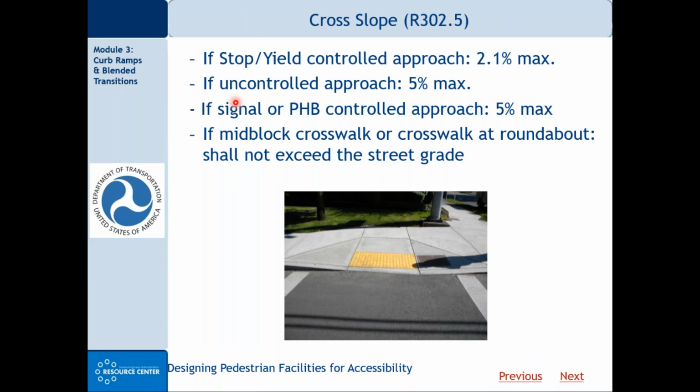But I would say it sounds like it's an area where technical infeasibility may apply. And so I would document that. I don't have it in this presentation. I use it in some other ones, but a few years ago, I attended an Access Board webinar, and I have a drawing. It shows, I think, going from the level landing to a street with a grade of 14%. And it shows how they transitioned that change.